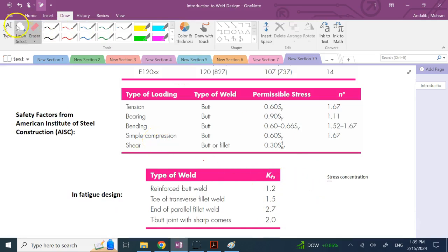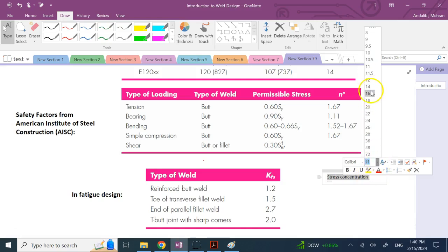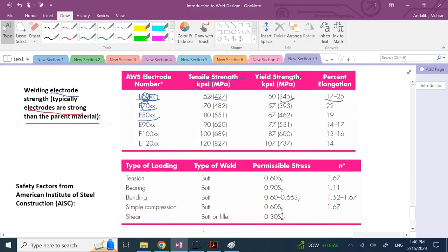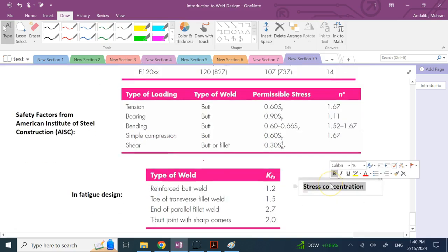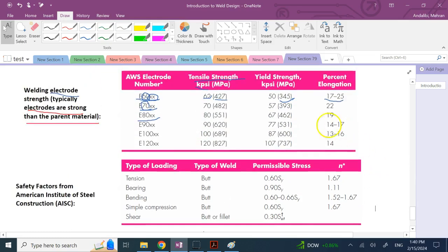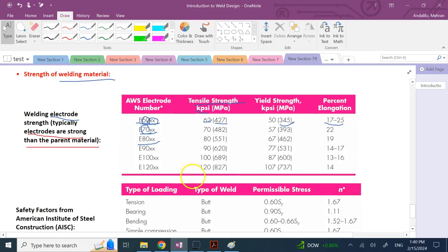That's why, in order to make a building stronger against earthquake, they typically connect the beams by bolts and nuts. In recent constructions, if you look at buildings, they connect the beams by bolts and nuts instead of using a lot of welding, because weld fails a lot easier against fatigue than bolts and nuts. Okay, I don't want to get into that topic, but just keep in mind that fatigue affects welding quite significantly.